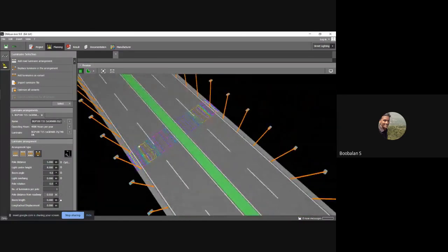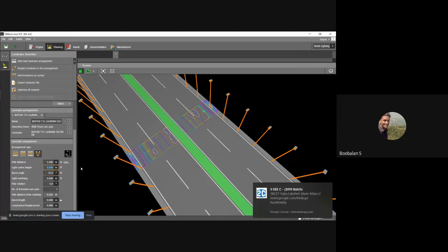See your lamp. This is the area of my flux light. I have given a 4 degree angle, so in this area the light illuminates and the flux lines are very high. But towards the grass area I do not get lighting. For that purpose I am going to increase my beam angle to around 10 degrees. Now see, my light is increased towards this grass area, right?